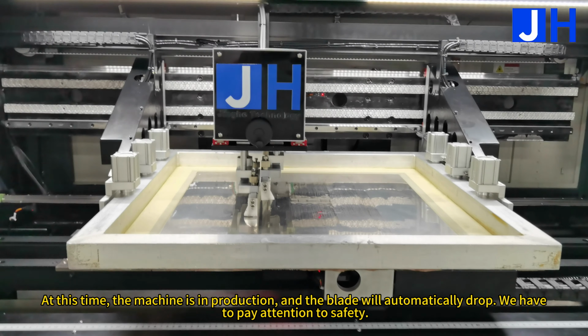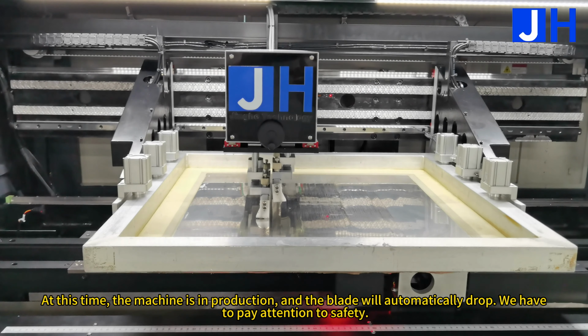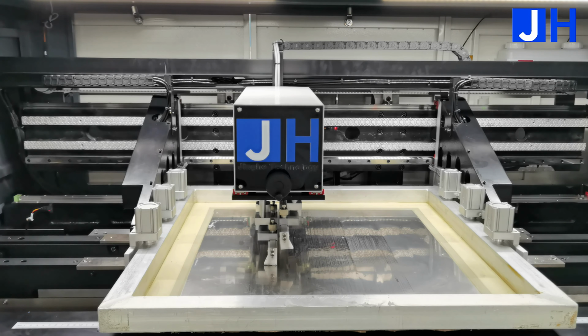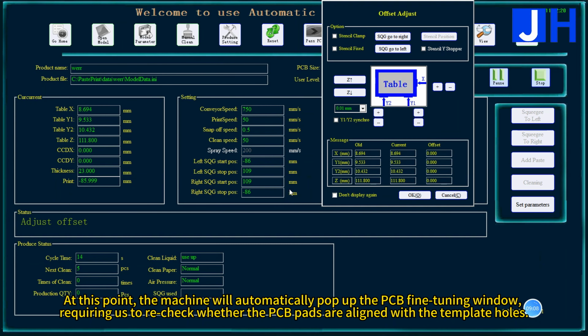At this time, the machine is in production and the blade will automatically drop. We have to pay attention to safety. At this point, the machine will automatically pop up the PCB fine-tuning window, requiring us to recheck whether the PCB pads are aligned with the template holes.